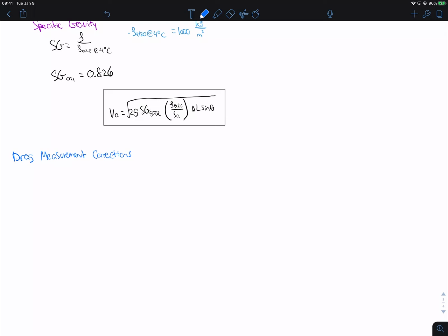So we're getting the drag on the object, but we're also getting drag on the support rod. So if we're looking at our reading for the drag or the lift, we're getting that total drag and that total lift. We don't want that, so we put in our object on the support rod at one point, and at a different point in time, we only put in the support rod. That way we can find the drag on that support rod, then subtract it out.